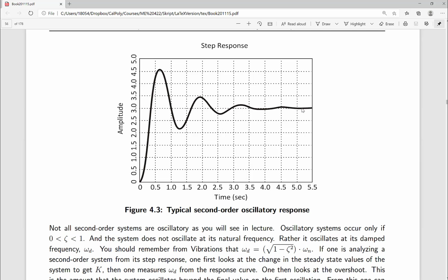So that's the problem with second order systems design. If you are designing a system that has a second order response and you only look at the static or steady state conditions, there may be a period in going from one to another where you actually have an excursion off into a zone that you hadn't designed the system for.